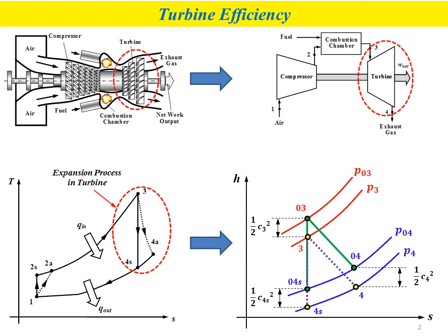Previously in thermodynamics 1, for the turbine we just considered static pressure, which is P3 at the inlet and P4 at the outlet. Now we have two types of pressure at the inlet of the turbine: stagnation pressure at the inlet, P03, and static pressure at the inlet, P3. We also have two different pressures at the outlet of the turbine: stagnation pressure at the outlet, P04, and static pressure at the outlet, P4.